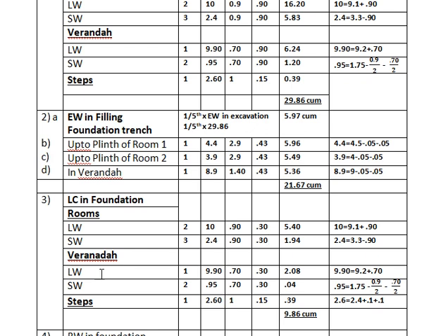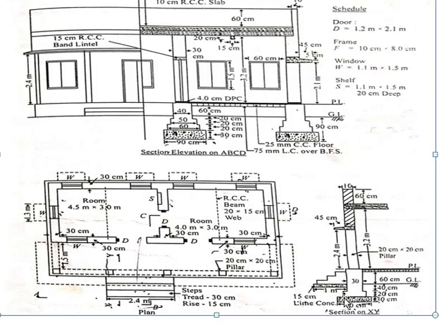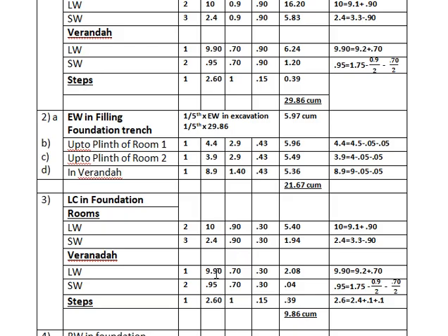Now talking about the veranda, which is important here. For the long wall of the veranda, you can see basically the length is 9.2, and we're talking about the lime concrete. Let me show you the plan. And this is the lime concrete. For the veranda, it is only for this portion 0.70, so we have to add 9.2 plus 0.7. You will get the 9.9 as the length of the long wall.